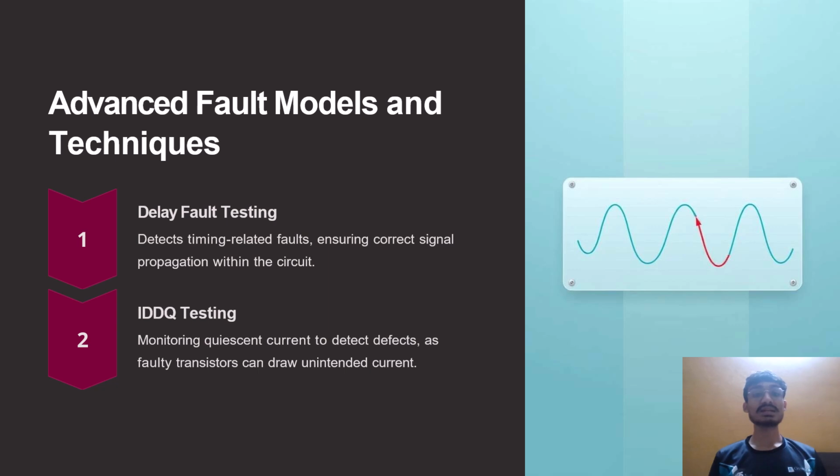Advanced fault models and techniques. Delay fault testing detects timing related faults, ensuring correct signal propagation within the circuit. And IDDQ testing, monitoring quiescent current to detect defects, as a faulty transistor can draw unintended current.